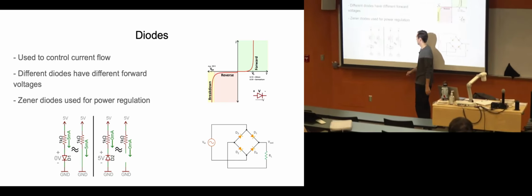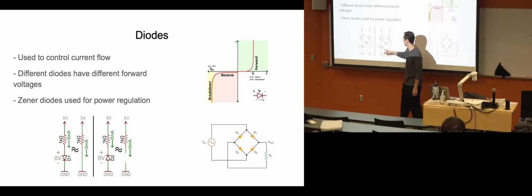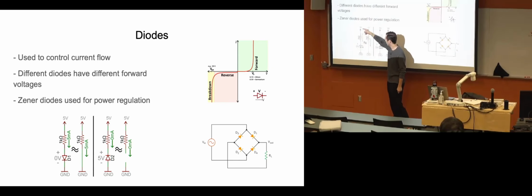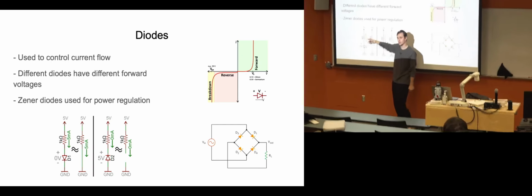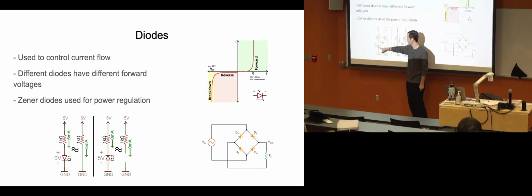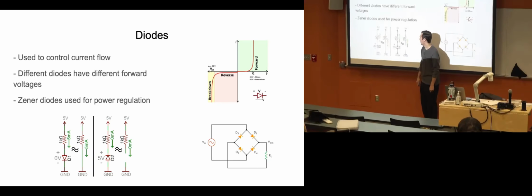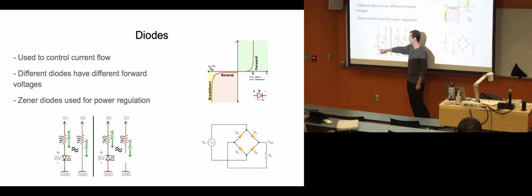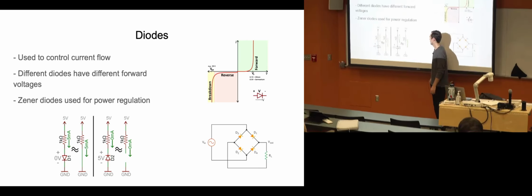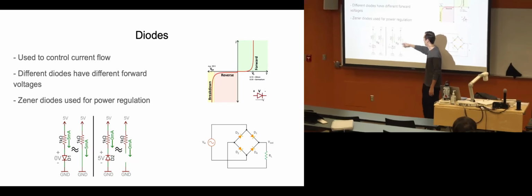So we have this first one on the left has a positive voltage up here, a current limiting resistor, and then a diode facing the right direction, right? So we're going to get, based on this calculation, 5 milliamps through this diode, through this whole circuit, right? We have the voltage drop as 0 here. It's not realistic, but this is just for teaching purposes.